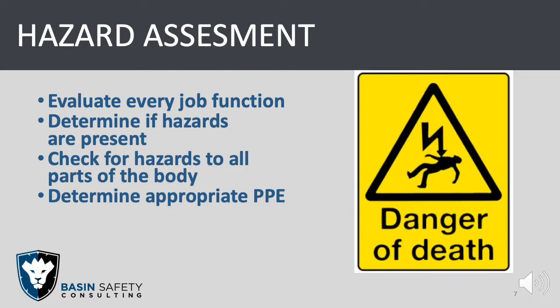So determining appropriate PPE is an important portion of this. But as we know, hard hat, safety glasses, steel-toed or composite-toed boots, some sort of glove for whatever task you're doing: impact, typically, sometimes cotton, rubber if you're working with oil. FR clothing, basically head to toe, can't be rolled up. No one's out here trying to wear a Hawaiian shirt around the treater. It's just, no one's doing that. We're in FR, we pretty much understand.